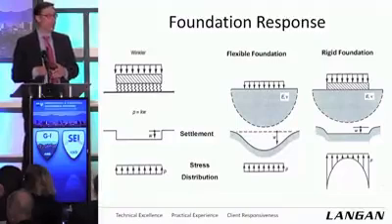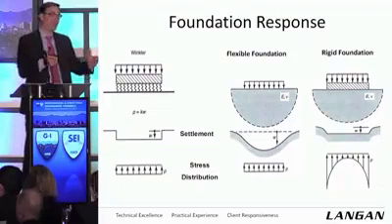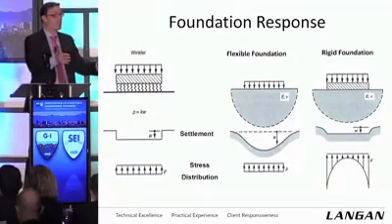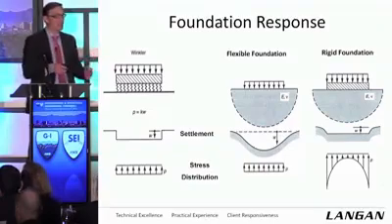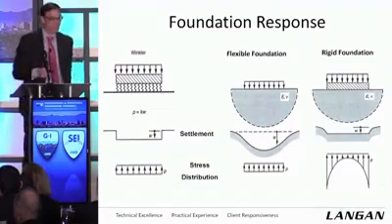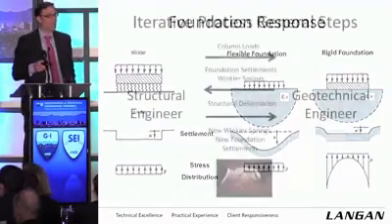pressure distribution. And of course, on the left-hand side, Winkler springs. Some thought, hey, if the loads are coming down, all the piles are the same, the individual pile springs should be the same, they'll be loaded the same, and the settlement will be the same. But it doesn't always work that way.